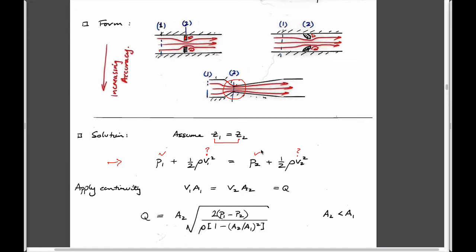It just measures it by having a pressure on either side with a membrane in the middle. Depending on which side is the higher pressure, the membrane, or the diaphragm, will buckle in that direction. You measure the displacement of it with a strain gauge, and you feed it into a data acquisition system to be able to measure the pressure differential. And so we can get either the absolute pressure or more likely the differences in pressure.